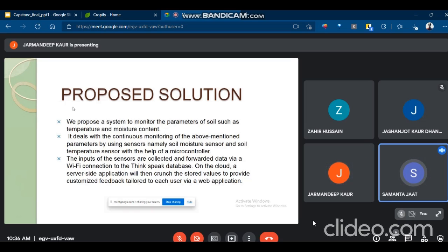We need a GSM or Wi-Fi network in the field to send the data to the server. Like we know, in the agriculture field, we don't have an internet connection, so for that, we'll be using the Wi-Fi or the GSM module. The receiver is built using an ESP32 Wi-Fi module, which has access to a Wi-Fi network. The data can easily be uploaded to the ThingSpeak server, and results can be analyzed in the form of graphs. By analyzing the graph, we'll configure the values of temperature and moisture, and we'll give the crop recommendation through our website to the farmers.